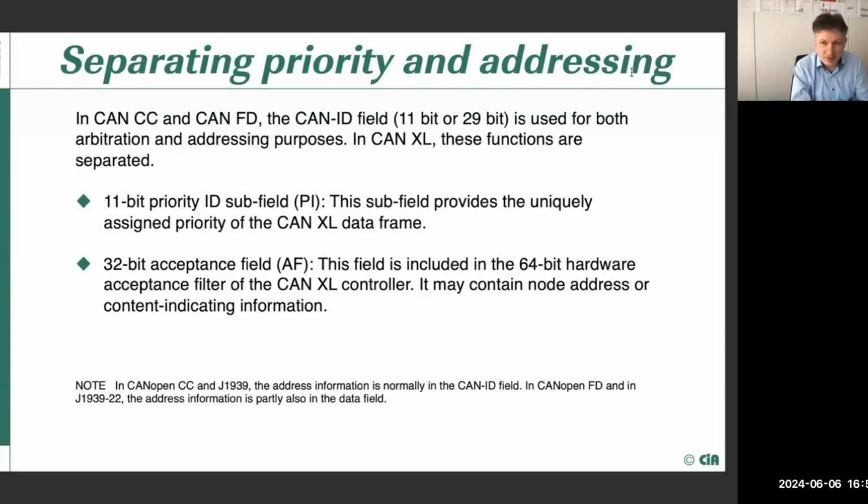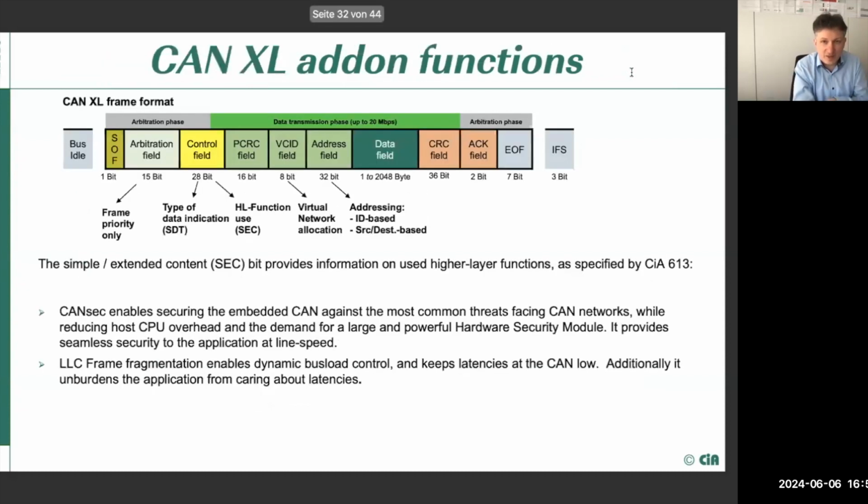So there is some necessity for the things that were introduced since CiA. This is priority and addressing. So priority says how fast the message should be transmitted. And the addressing field says where the message should go. In a routing table, in a gateway, this information will be provided, and the gateway will be routing the message, getting this information exactly from the frame itself.